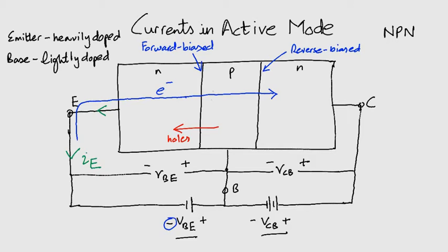So, because of this positive voltage here, the electrons are going to be swept across the collector base junction and therefore will be collected at the collector terminal. Obviously, the electrons are not collected in reality but continue flowing on into the collector terminal. The term collected is to signify that these electrons were saved from recombination in the base region. On your screen I have shown the direction of the collector current.